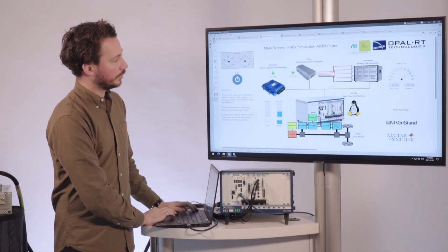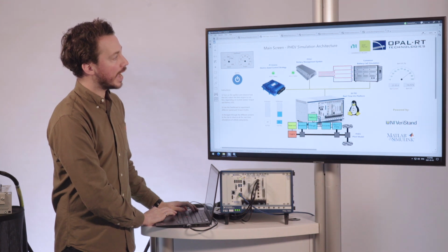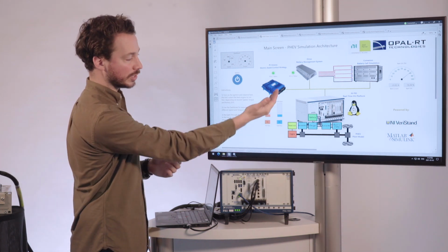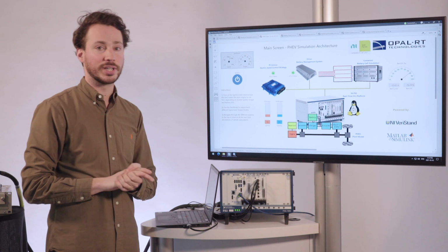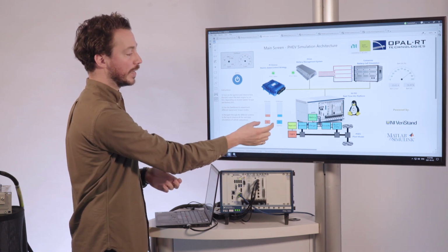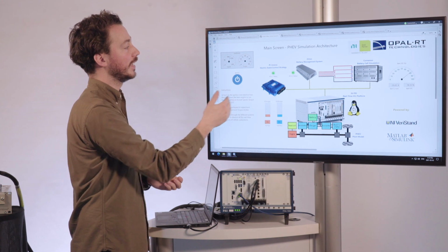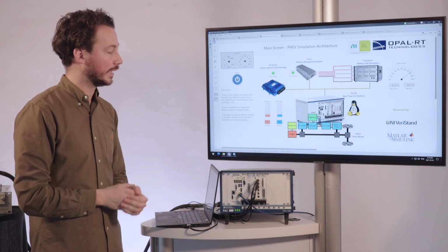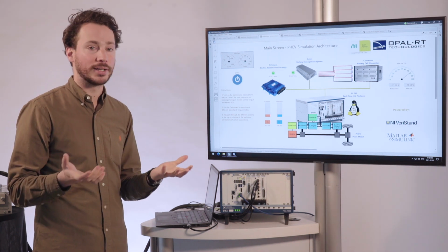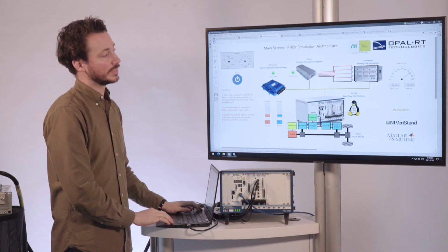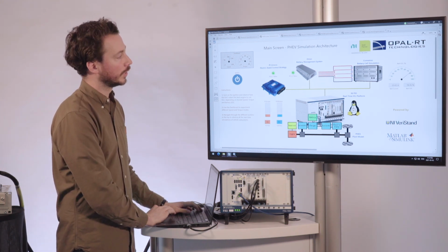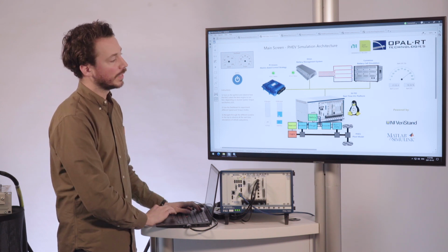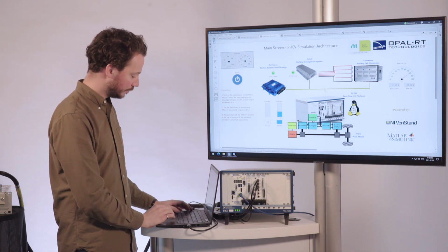And then at a certain point, for example, if you go at a speed that is too fast for the electric machine to handle, you can see here that we've swapped now between not just electric machine torque, but as well as the combustion engine. This decision is made because the Pi-Innovo has detected that there is too much speed required for the electric machine to actually produce. So it has switched the powertrain, and now we have a parallel combustion engine as well as electric machine providing the power. So I'm going to lower the speed again. Now we're stuck basically just with the electric machine. And with this, I will now go to the next tab.